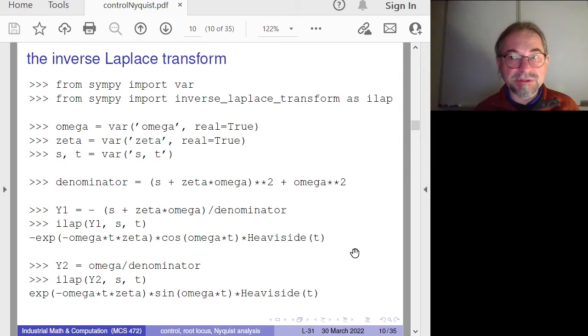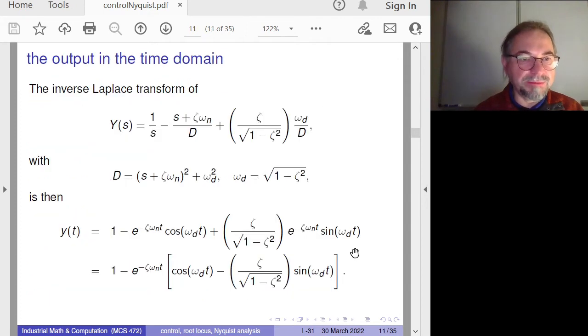In a way, the inverse Laplace transform solves the general behavior of this mechanism. We do have a decay, and we do have the 1 as the equilibrium state. This is clear from the formula at the bottom. At the bottom we have the 1 right up front, and then we have the time that is positive and in the long term goes to infinity. So we have this decaying exponential, and you can see that the zeta in particular will determine, and the zeta better be between 0 and 1 because of this denominator there, how fast we go down, how fast the decay is.